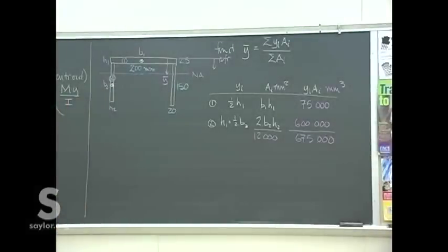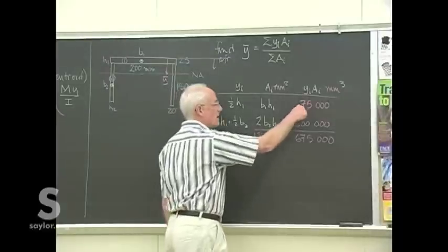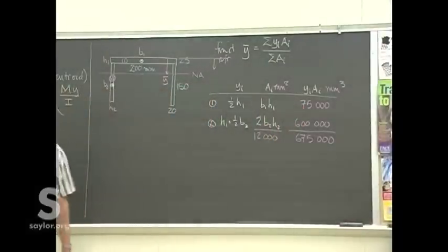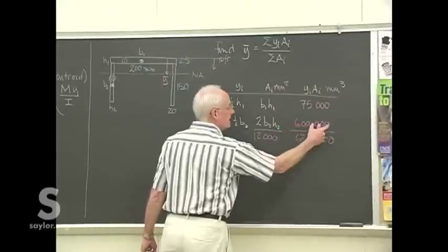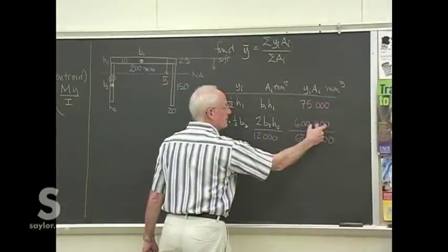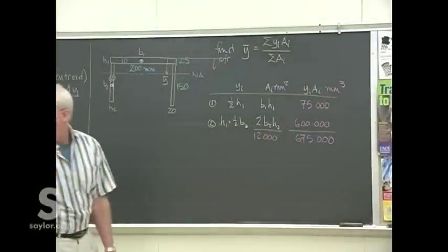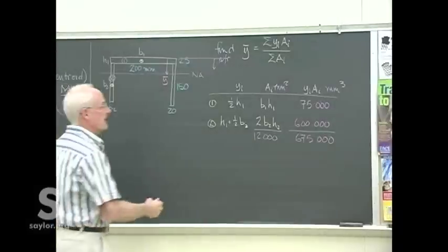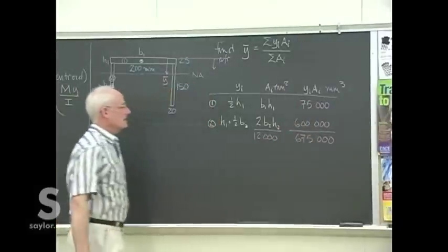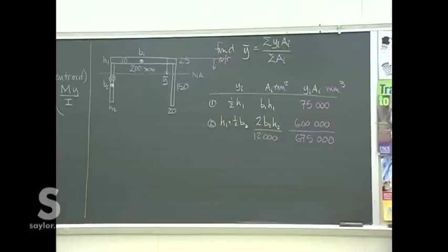In lots of European countries, they see commas as decimals. So it's very hazardous for us to use commas if somebody that we might be working with in Europe would see that as a decimal and have a completely different number for their design. So if you just leave a space, you get the benefit of that grouping by 3s that keeps the mistakes down, but there's not a misinterpretation of what a comma or a decimal might mean.